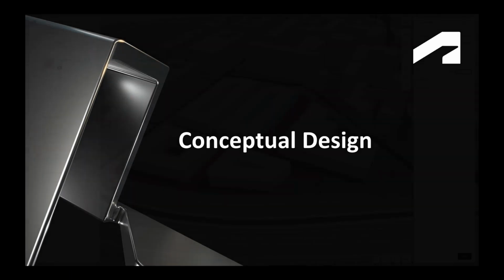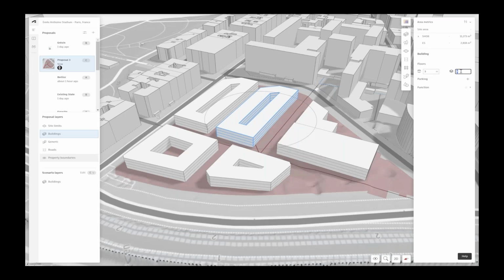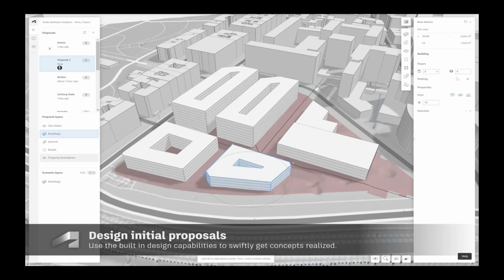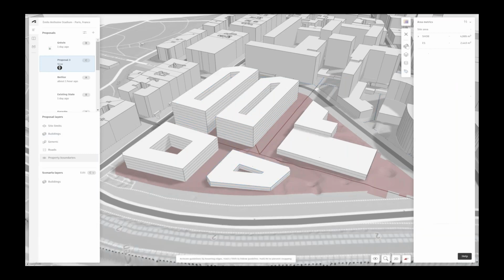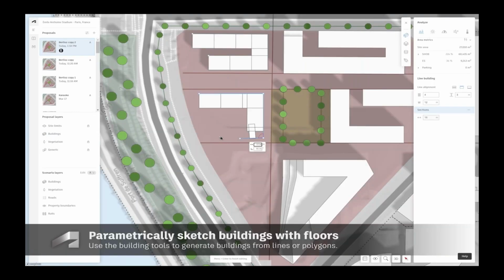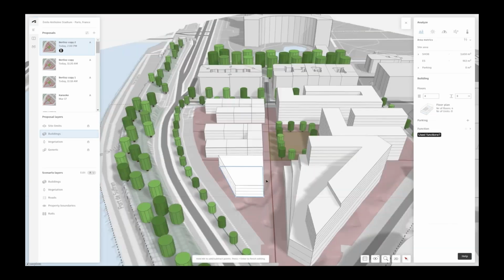Once you have the terrain data, we have tools to create the conceptual design. When I say conceptual design, the design can be created at an initial stage where you will be able to create blocks, like volumes or sketches, which can be created like cubes, and you can also rotate and modify them as you want. This creates parametric sketches which will help you see the familiar buildings nearby.